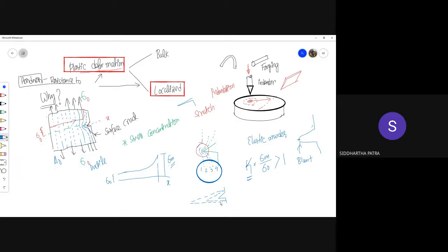So we need to give special importance to this type of hardness and this type of plastic deformation. If indeed there is a scratch on a glass component, that can be severe. You want to prevent a scratch or an indentation on a brittle material as far as possible, and therefore you want to improve a certain property, and that property is hardness.